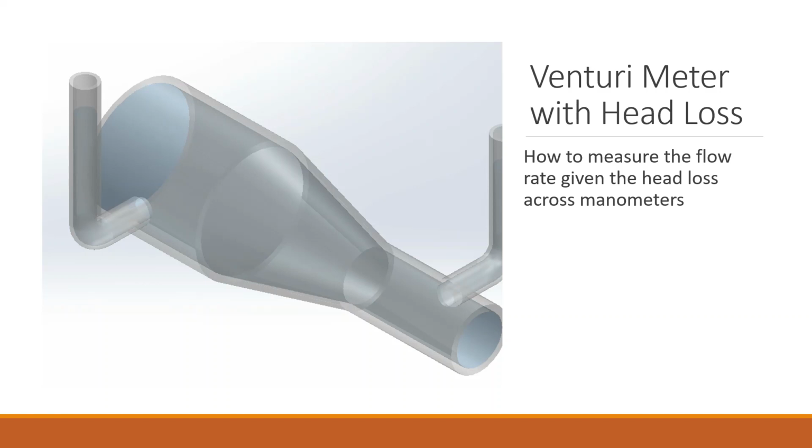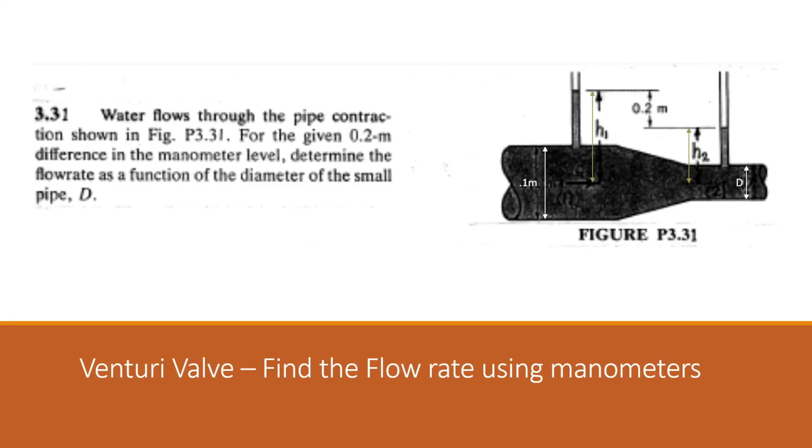Lab 3 is essentially using the Bernoulli equation through a Venturi meter, and you find out that, hey, we have unaccounted for frictional losses that show up in the static pressure or the static head that you can directly measure. So, apologize for the graininess and lack of color. I was not given the high-res version with color, so here we go.